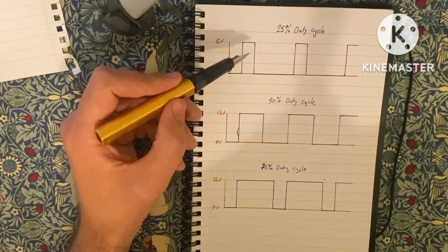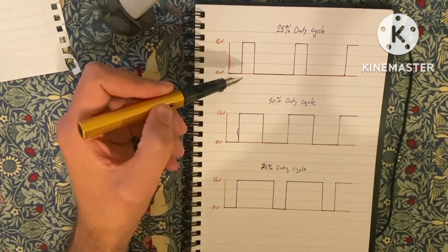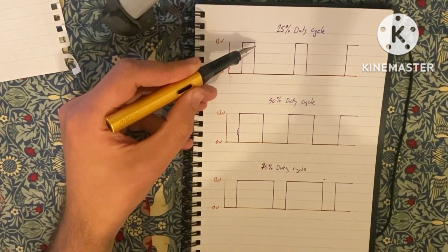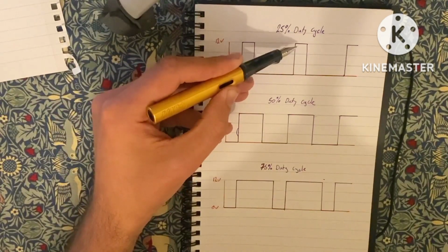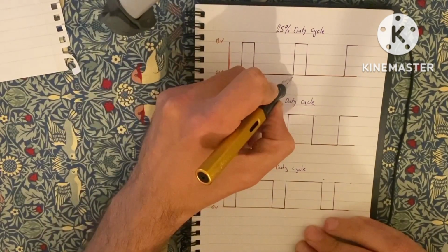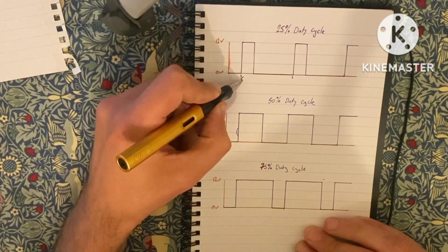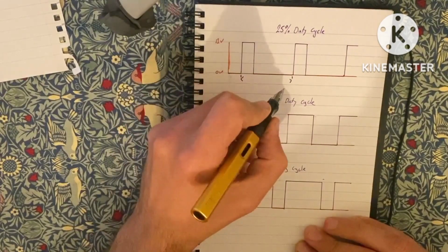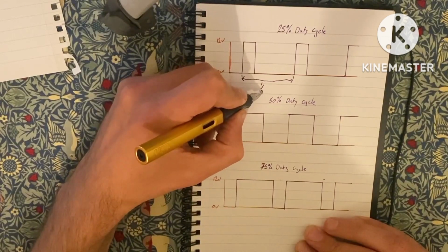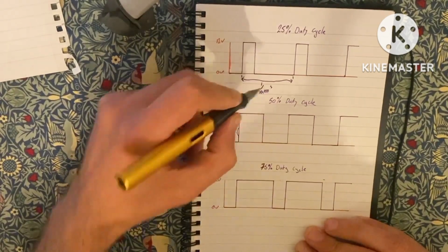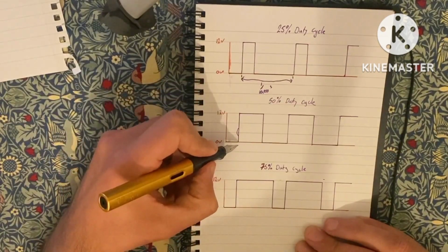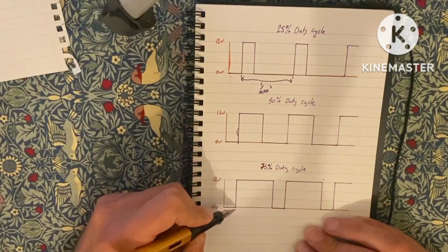So we'll notice that when we measure a pulse, we measure it from what's called the rising edge. So this pulse comes along here, then it rises up, goes along, drops down, goes along, rises up, goes along. So we're measuring from this point here, the rising edge, to this point here. And because this board operates at 10 kilohertz, this here is 1/10,000th of a second.